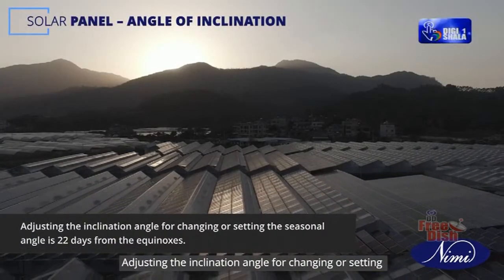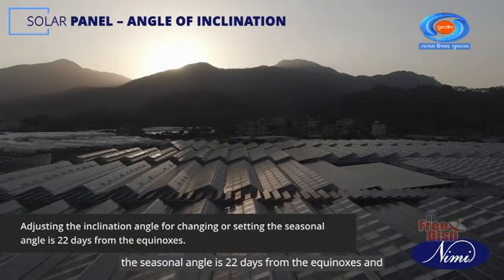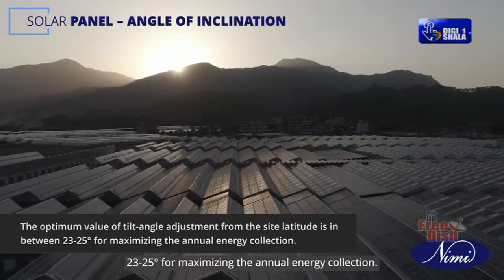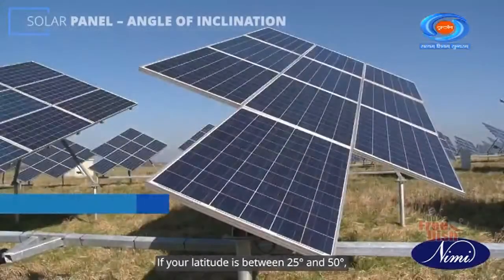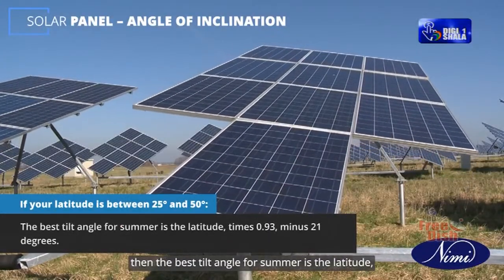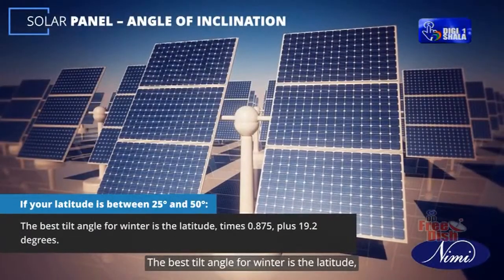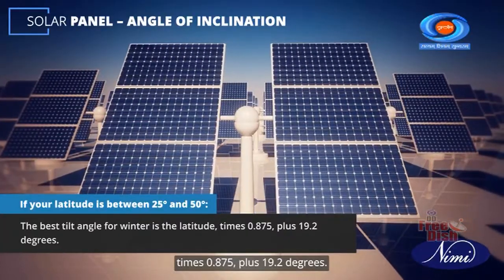Adjusting the inclination angle for changing or setting the seasonal angle is done 22 days from the equinoxes, and the optimum value of tilt angle adjustment from the site latitude is between 23 to 25 degrees for maximizing the annual energy collection. If your latitude is between 25 degrees and 50 degrees, then the best tilt angle for summer is the latitude times 0.93 minus 21 degrees. The best tilt angle for winter is the latitude times 0.875 plus 19.2 degrees.